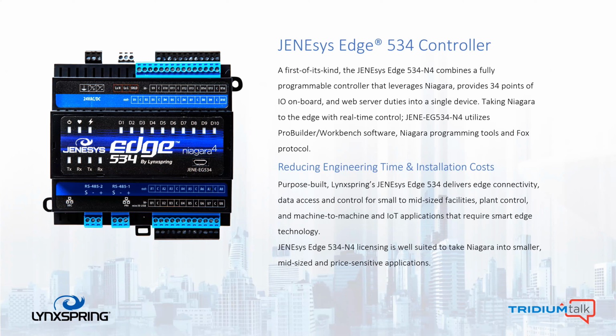It also can work within a bigger Niagara network. It can be a standalone IP controller, it can be a standalone serial controller. It can be a slave within a BACnet network. And it's available in a retrofit kit to replace existing J2, J3, J6 installations when you're using a wiring cable set that we have available. Next slide, please.